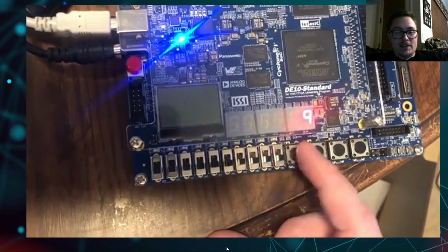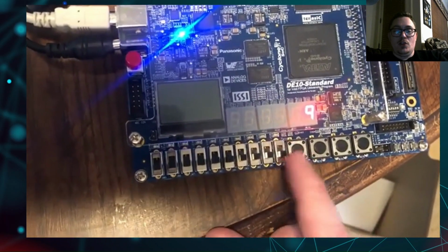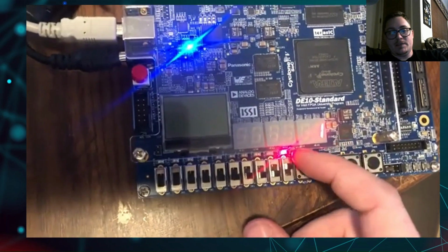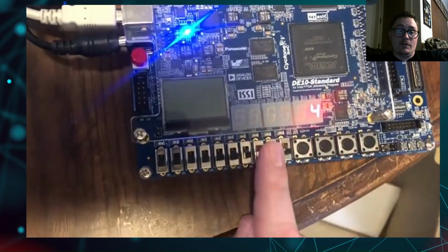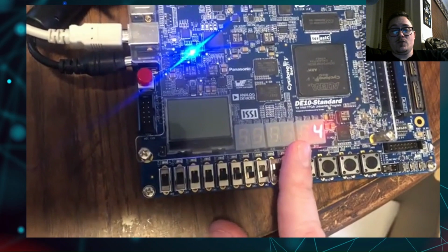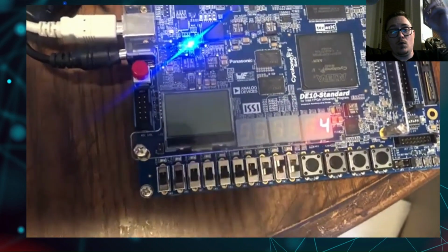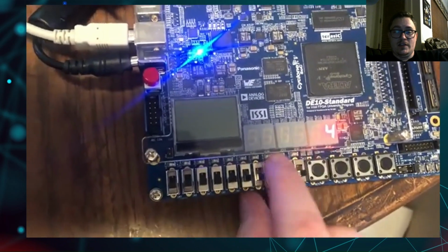Now, by default, that switch on the very end on the right is low, and that means the operation is addition. But as I flipped it high, we saw that it was subtracting, 5 from 4 being 1, and that second switch went high for us to AND those two values. And obviously 5 and 4 share that 1 in the 4's place, and so that's why we see 4